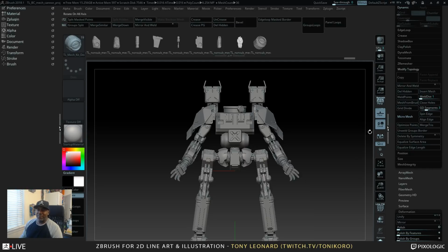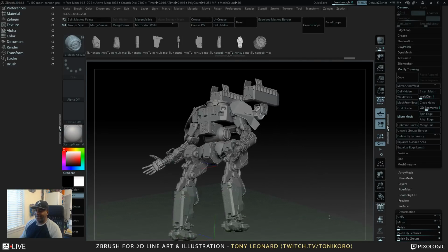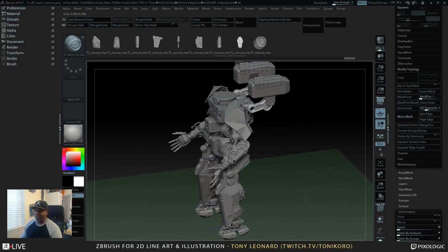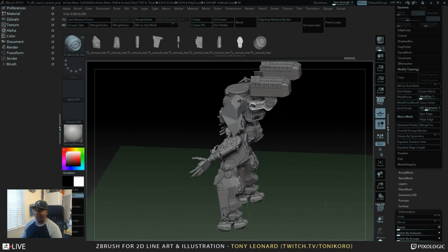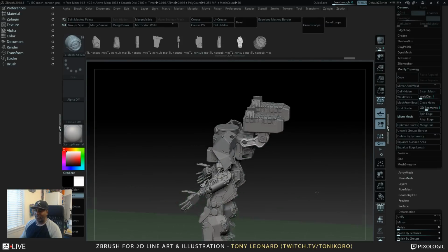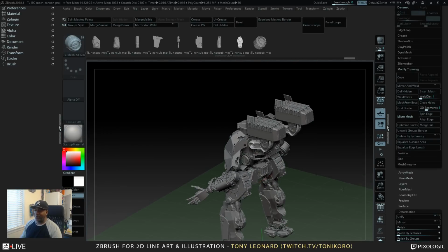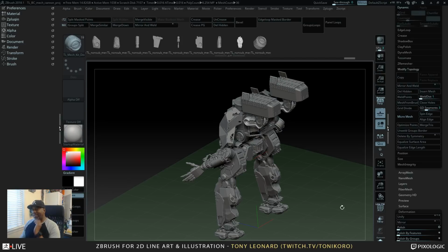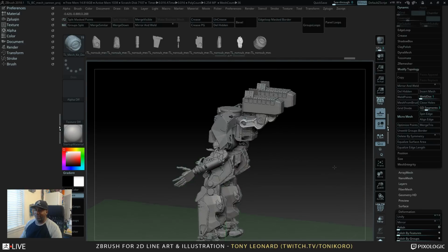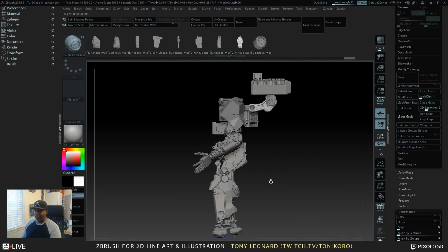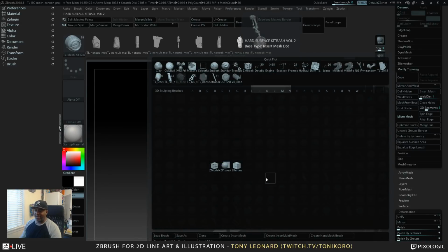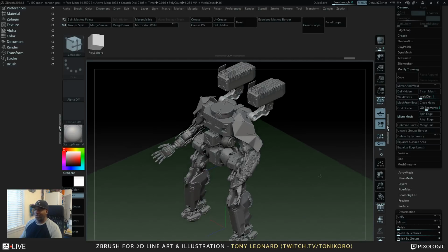Alright. So, as of late, I've been hooking up a lot of things using both ZBrush and Blender, jumping headlong into a 3D package to use for a lot of poly editing, building of silhouette shapes, and major forms. For a lot of that I've been depending on two different approaches, and one being, and I've probably run through this before in the last couple of months in some ZBrush Lives, the ZModeler tool. It usually depends on hitting B on the keyboard, then Z, and then going to the ZModeler tool and working on an initialized cube.